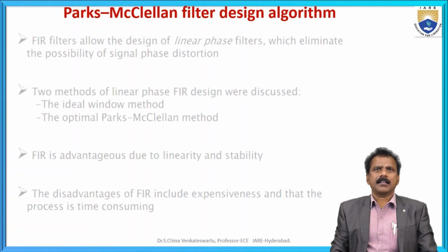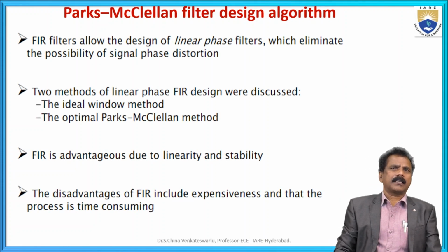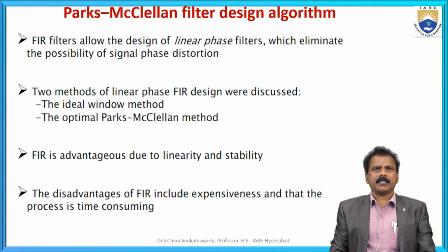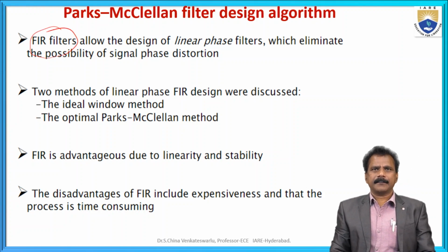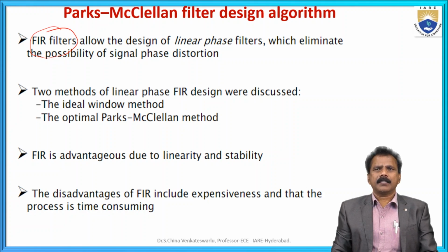In this case, FIR, finite impulse response filters, allow the design of linear phase filters. Already we have proved this mathematically and practically by using MATLAB software, which eliminates the possibility of signal phase distortion. Two methods of linear phase FIR filter design were discussed already.